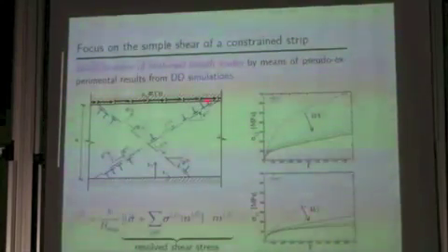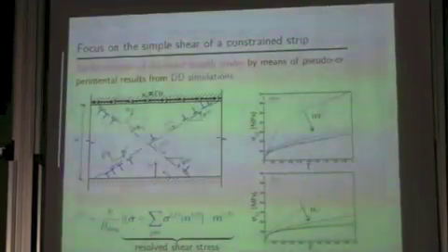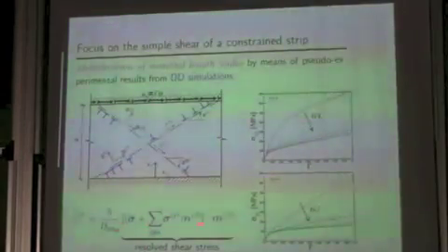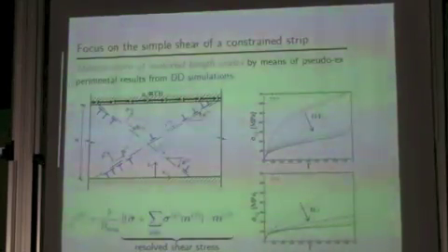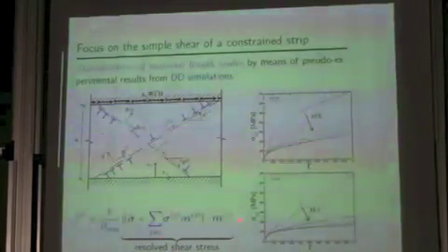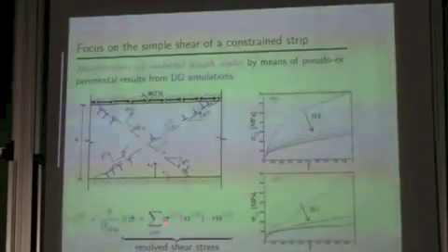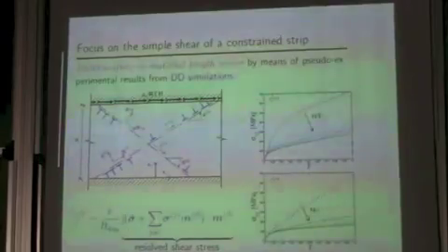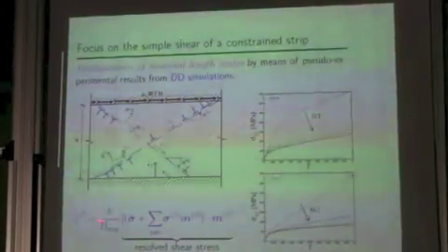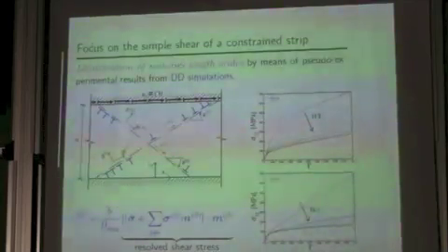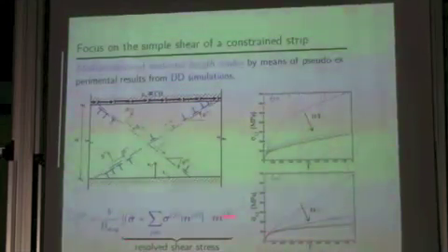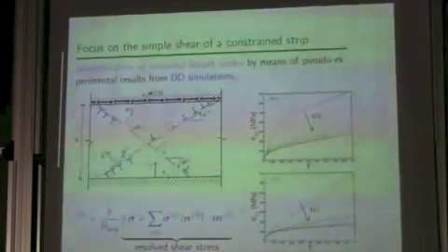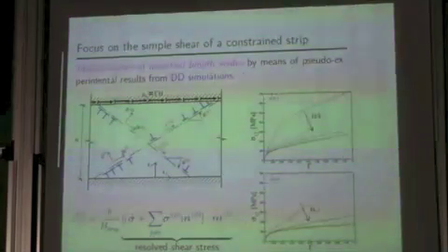And the main equation governing this discrete dislocation dynamics is this one, in which you compute the velocity of each dislocation in its slip system, and the resolved shear stress is due to the singularities of all the other dislocations within the sample, plus this sigma hat is due to the boundary conditions and to some image tractions you apply on the boundary of your finite element simulation to compensate the fact that these stresses due to the singularities of other dislocations are in an unbounded medium.